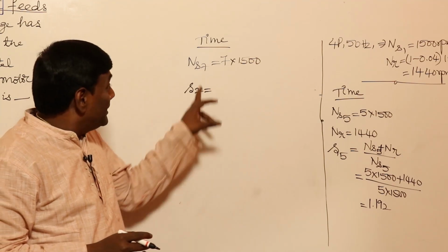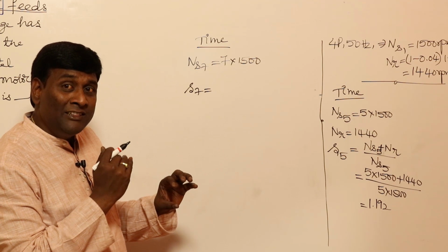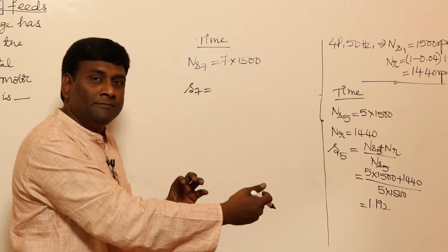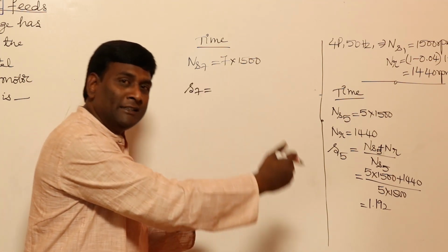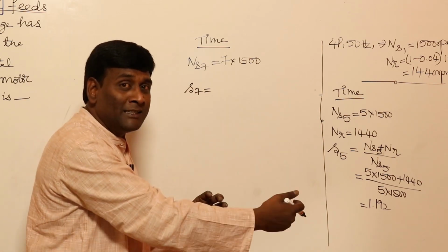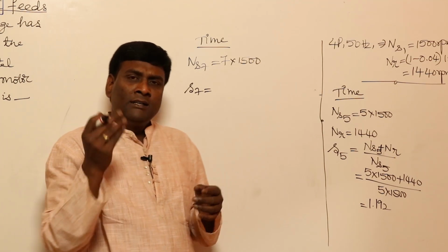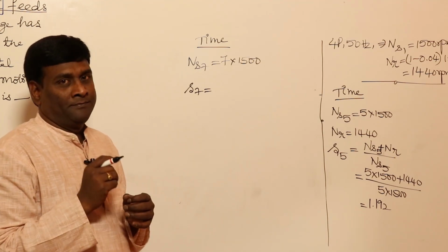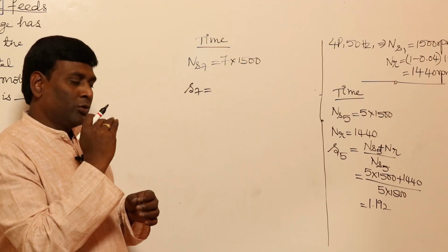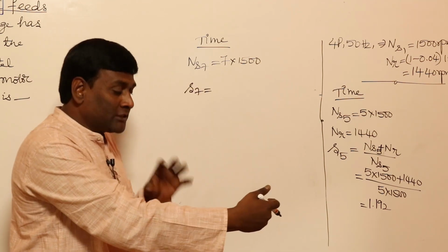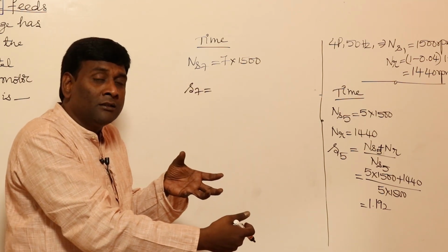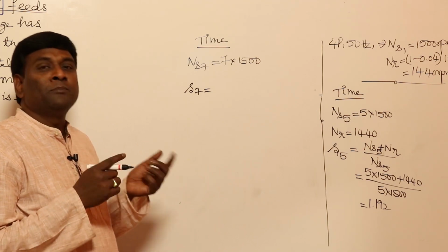The seventh harmonic component will be aligned with the phase sequence of the fundamental. So the fundamental is rotating in this direction, so the seventh harmonic also will rotate in the same direction because we have to use plus in the generic equation h equal to 6n plus or minus 1; 6n plus 1 is going to be 7. So the RMF is rotating in this direction, the rotor also is rotating in the same direction, so relative velocity should be ns minus nr.